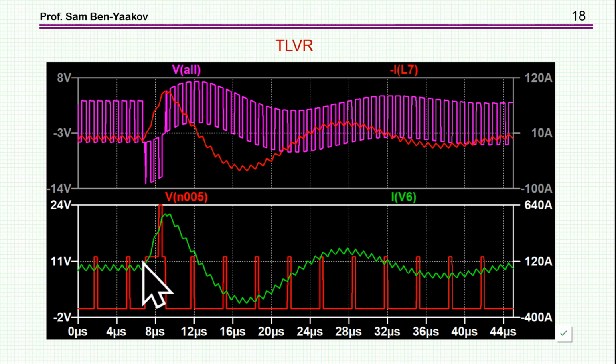This is the IDT resulting from a disturbance in the duty cycle or in the PWM signal, you might say, and this is affecting a half bridge. And as you can see, we see a change in the order of, I'd say, 400 to 500 amp in these 2 microseconds. Here, this is 2 microseconds, so I have a change of 400 or 500 amp. That's quite a lot, of course, depending on the system. This is a high current system.